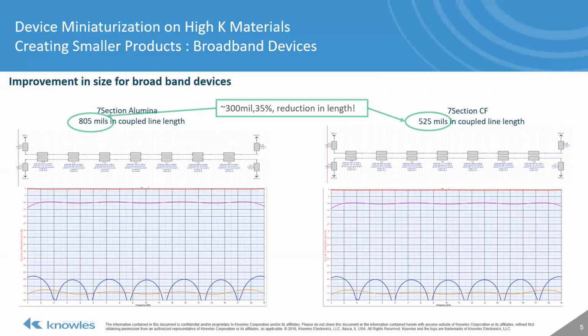If you remember from the microstrip theory slide, effective K is really what's going to drive your size in microstrip technology. So here we use an approximate model using effective K as a homogeneous substrate. That's really going to provide a good estimation to compare the sizes and differences in K, while still being able to maintain the performance that we're looking for.